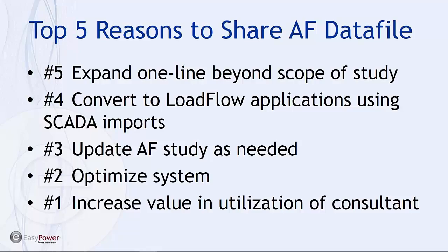The ability to convert that ArcFlash database into a more realistic database using SCADA data allows me to do load flow applications and expand on more knowledge of my actual system for both analysis and what-if discussions.